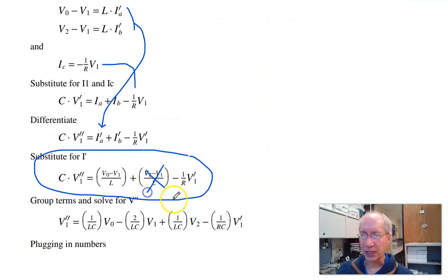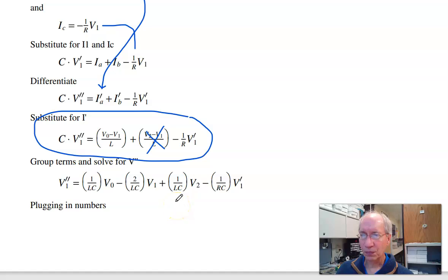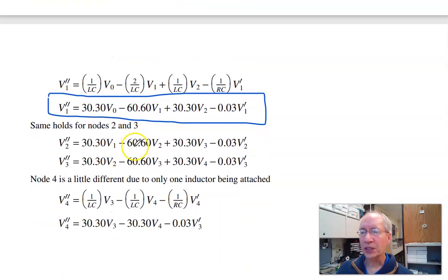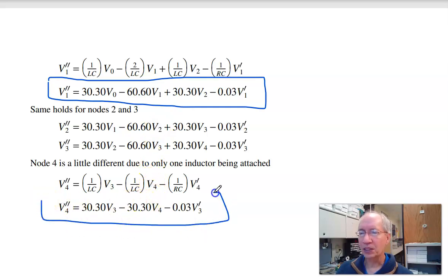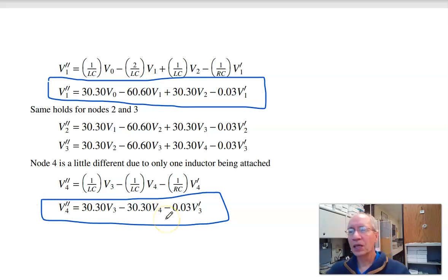This term disappears on the last node. And so you wind up with just 1, and this term goes away. That's at the last node. All the equations are the same except for the last node. The last node's the oddball. This is a slightly different equation. So what I'm left with is, with an RC circuit, last week's lecture, my circuit was described by coupled first-order differential equations. With an RLC circuit, adding inductors, my circuit is described by second-order coupled differential equations.